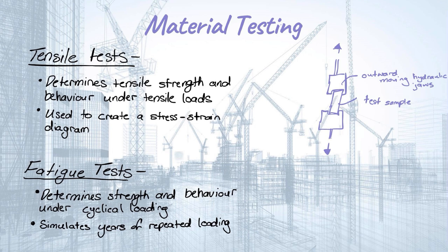It is done by putting a specimen in between two hydraulically activated jaws. It stretches the specimen until failure point, and this is used to create a stress-strain diagram, and it determines the characteristics of the material. Fatigue tests.